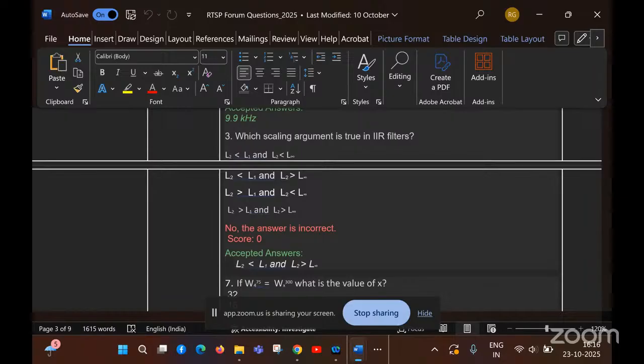I'm talking about fixed point. I have given the explanation of why we went for fixed point. In an FIR filter, we assume that the input is scaled, so the magnitude of the input signal is 0 to 1. So the coefficient magnitude should be less than or equal to 1, as we said. And in an FIR filter, we can allow a little bit of overflow and other things.